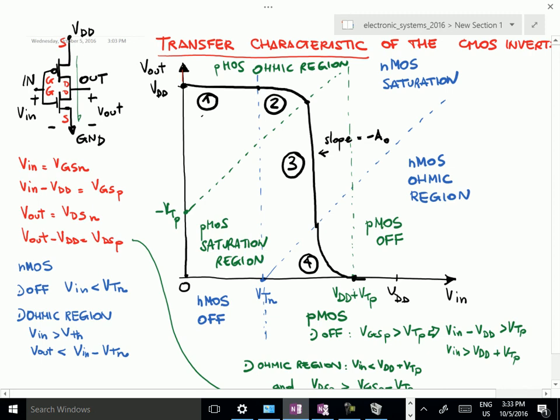So it is at 0. So this is the transfer characteristics of the CMOS inverter. It's really different from an ideal switch that we can imagine. The only situation in which the output is 0 or VDD are the branches 5 and 1, but between 5 and 1 the output voltage goes as a continuum from 0 to VDD.